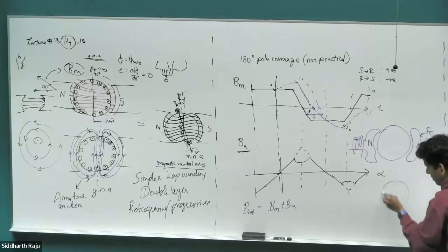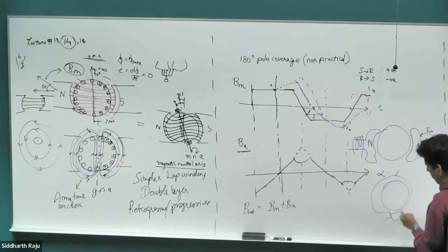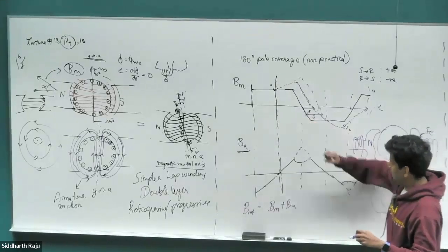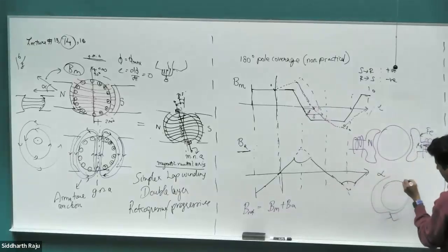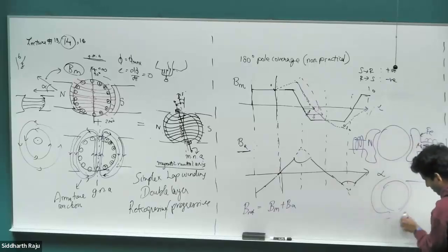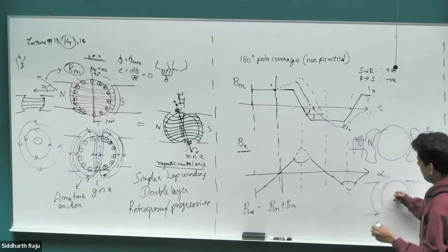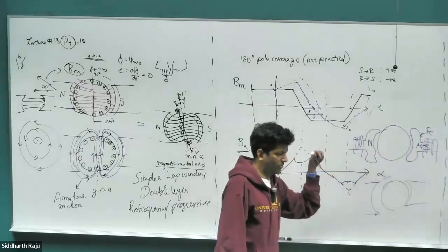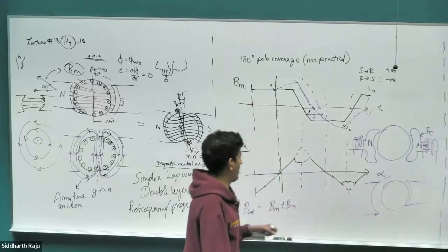When you have magnets, if you have a neodymium magnet, it absolutely doesn't matter whether you have a full spread or no spread for the armature reaction component. It still matters for this BM component, it doesn't matter for the armature reaction. When you have a ferrite magnet, it does matter, not as much as this iron core, but it's still not as bad as a neodymium magnet because the mu r around the operating point is around 100 for a ferromagnetic material. For a neodymium magnet, mu r is around 1. For iron core, mu r is around 6,000. Okay? So it still matters for ferromagnetic alnico magnets, ferrite magnets.